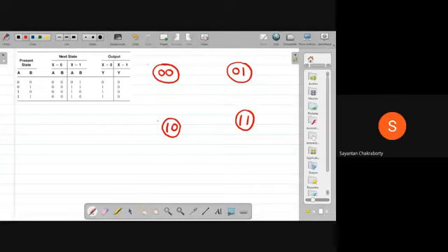Okay. So let us see if the present state is now 0, 0. And if you produce an input x equal to 0, then what is the next state? It remains at 0, 0. And what is the corresponding output for x equal to 0? The corresponding output is also 0. So this is represented by a line like this, where it will have two indices, that is 0 is the input, followed by slash, followed by another 0, that is output.